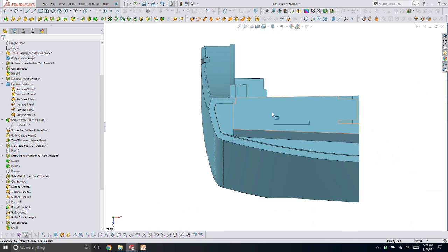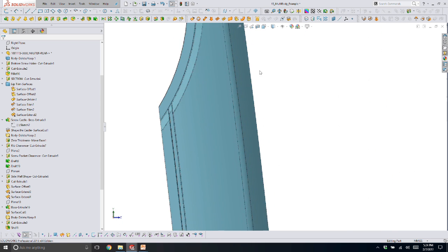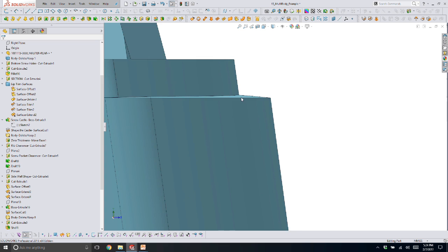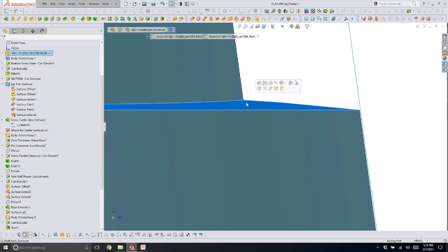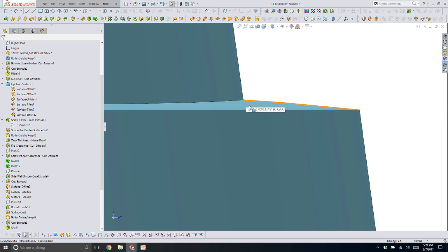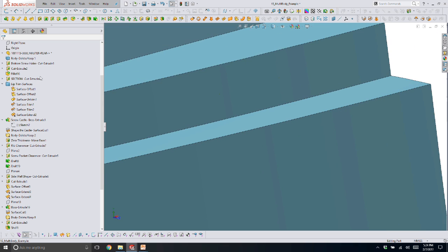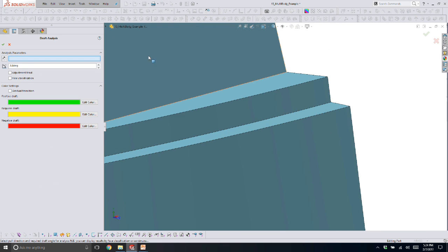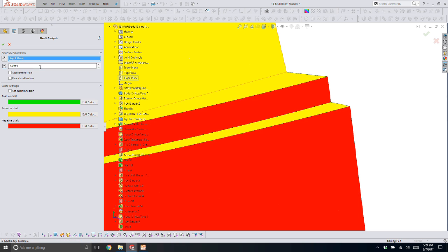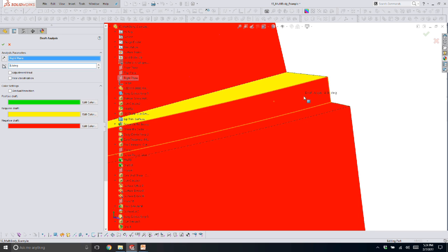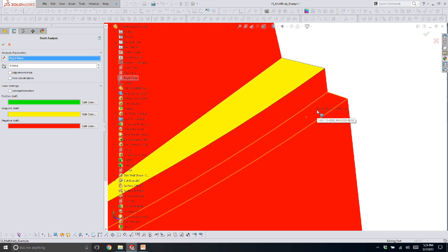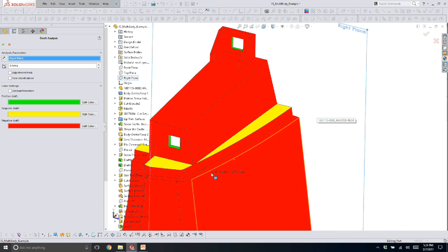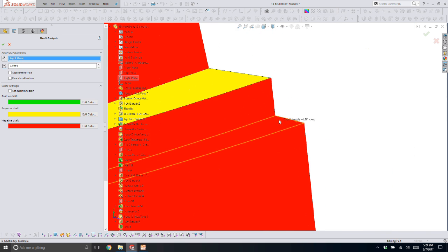And you'll see, in order to make this work behind the scenes, SolidWorks is applying the edge from that draft, and here is where we're actually getting the draft built in. So this edge is now kicking up significantly, but I have a half degree, and I'll prove it to you with draft analysis. So you can always draft a long chain of edges at a low degree, a half, 1 degree, if you pick the entire perimeter of edges. And now I've added much more material here as this edge kicks up, but I've got a clean half degree